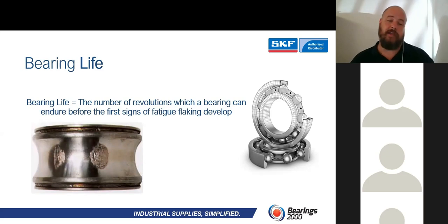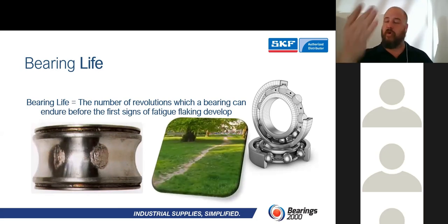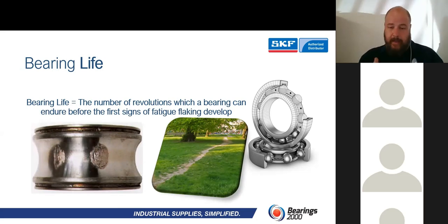That bearing is tired, it's finished, it doesn't want to run anymore, it has done enough. It is the same as when everybody has somewhere in the neighborhood a field with a path through it, whether to the corner shop, the park, or school. As you walk on that grass the whole time, eventually there is no grass between your feet and the soil anymore, and it starts to look like that. That is fatigue, and that's the same within a bearing. So bearing life is only the amount of revolutions we can get out of it.